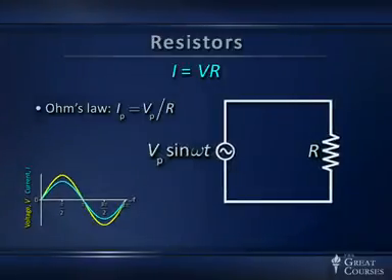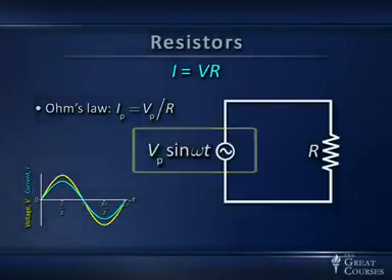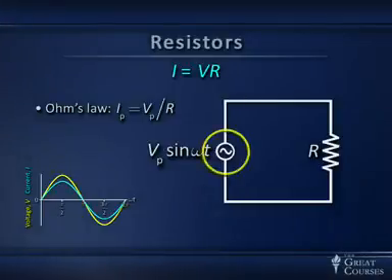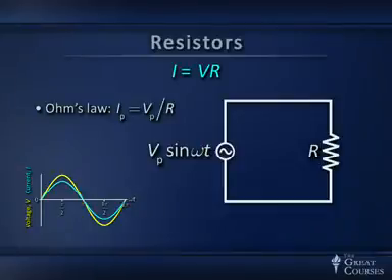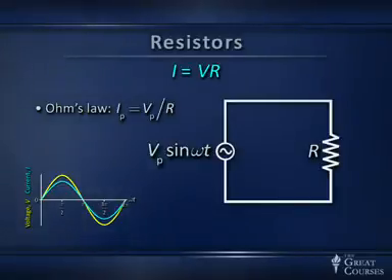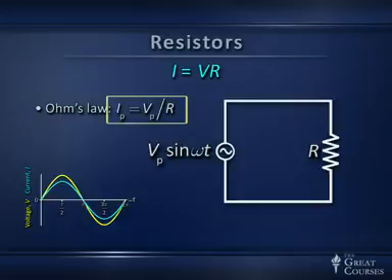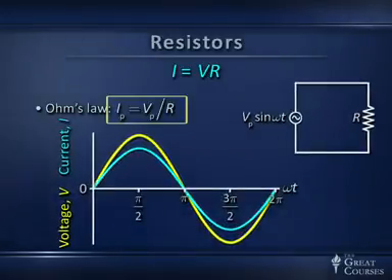So in the little circuit I've shown here, I've got an alternating source, and the symbol for an alternating source of voltage or current is a circle with a kind of sine wave in it that takes the place of a battery in this particular circuit. And in this utterly simple circuit, the source of alternating voltage is connected across the resistor. The resistor current and voltage are in phase. That's what that equation says. It says at any given instant, the current is the voltage over the resistance.